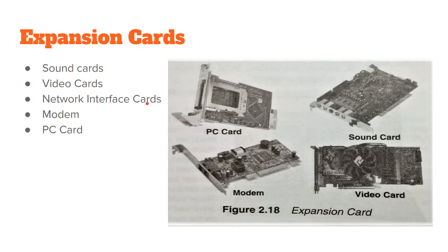Next is the video card. So what does this video card do? The video card is called the display adapter. It displays graphics in an enhanced mode on a computer monitor, and it converts the images created in the computer to the electronic signals required by the monitor to get high-end video. You might have seen monitors with high definition. So you need a video card for that. If you are using a laptop or a computer to get that, then you need to add an extra video card.